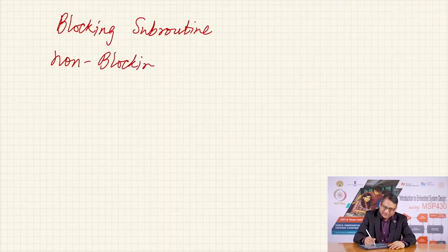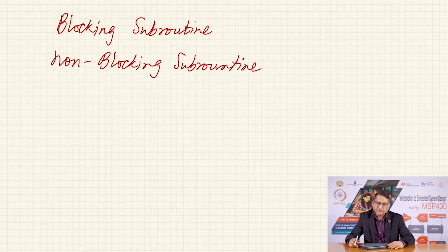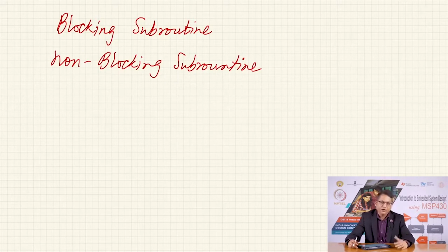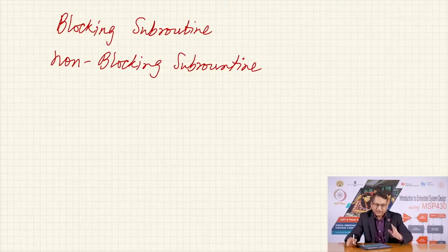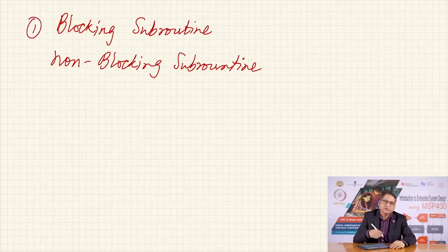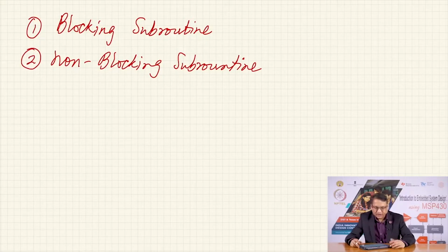Although we have not explicitly discussed this in our lectures till now, this is a good time to talk about it. Now, in the programming exercises that we covered here, the reading of the switch was in the main program, but you could as well offload it to a subroutine, and you could write the subroutine in these two fashions. You could write the reading of the switch as a blocking subroutine, or as a non-blocking subroutine.